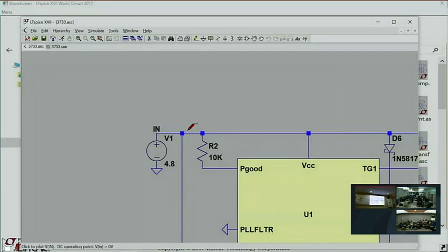What's the change in the output voltage? Well, zero, of course, because this flip-flop stays on long enough for the peak current to ramp up to a fixed current. Whatever duty cycle is necessary to ramp up to that peak current is how long this switch stays on. Then it disconnects the switch and it just reads out that energy in the inductor. This circuit is only integrating the volt-seconds across the inductor to ramp up the desired peak current. What waveform was across those volt-seconds doesn't make any difference. This thing has infinite line rejection to a first approximation.